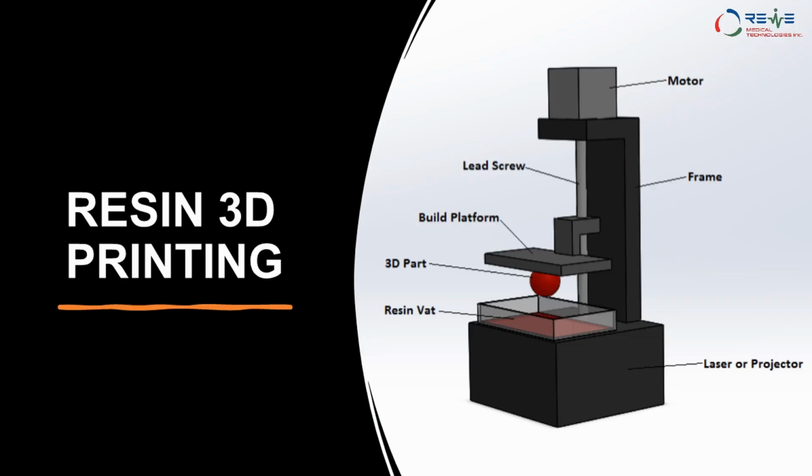We also have a resin 3D printer technology at our end. So just to give a brief layout of what resin 3D printing is, basically it is an automated machine which has a bath which is called a vat, which is placed onto a base which has a laser or UV projection system underneath it. And on top of it, it has a build platform, also called a build plate, which is attached to a computer controlled actuation system.